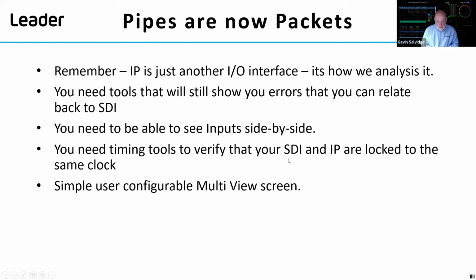Even the facilities that say we're an IP facility, you go in there, you'll find some SDI sources floating around. Oh, yes. You'll find a black and burst reference or tri-level sync still inside that building. The gateway products are now very good, but most of the issues we see are as this video, audio and data transitions from one timing plane to another. We're going from black and burst and tri-level sync into a world of PTP.